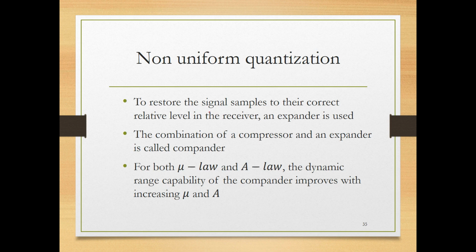Now, suppose you performed non-uniform quantization and you sent your signal. You must inform the receiver that you have performed A-law or mu-law compression.